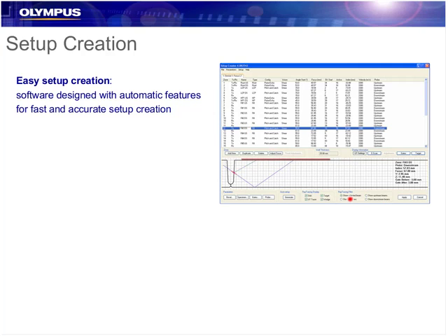And then typically for the first job, the first inspection, we would go over the cal block and maybe make some micro adjustments while being somewhat static over the reflectors and then running over it dynamically. And there's a lot of tools built in to make this very quick. So once we get in, we're able to see that the software will automatically generate for us the proper beams, both on emission and where they're going to be received, and the grouping of elements that are going to do so. There's a few more illustrations.